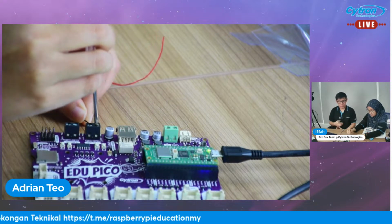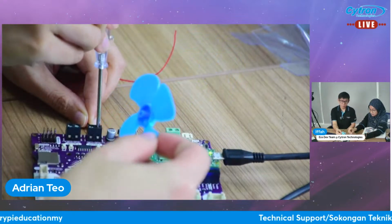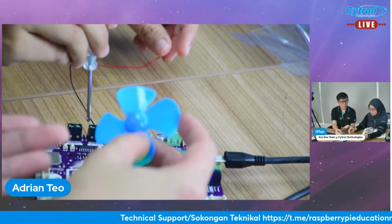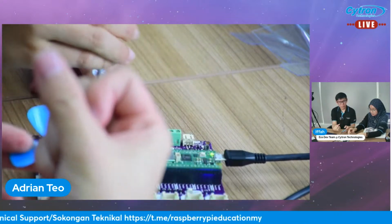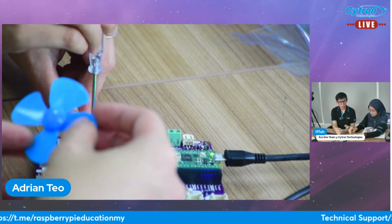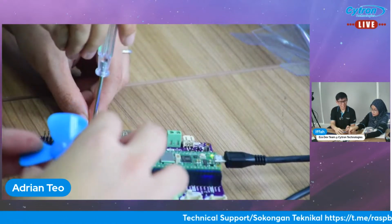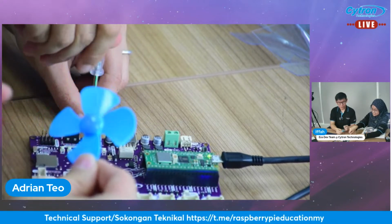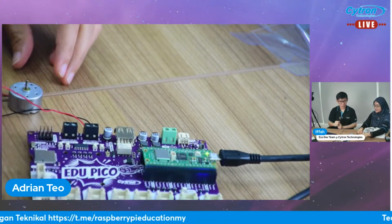It becomes sensitive if you are connecting components like a fan blade. By moving in a single direction, you're actually blowing wind, and by moving in the other direction, you're actually drawing wind. So if you attach the DC motor in the wrong direction, then your fan is not blowing, it's just pulling air in. It becomes like a ventilator instead. So that's where the polarity becomes important.